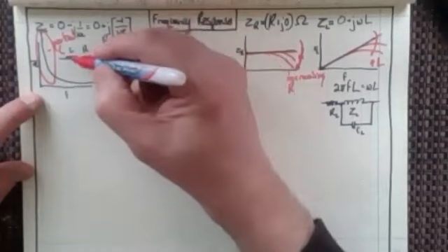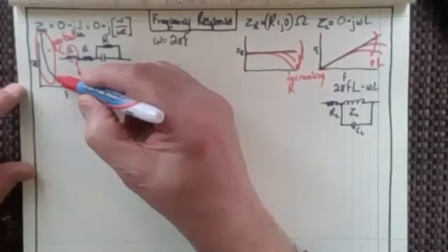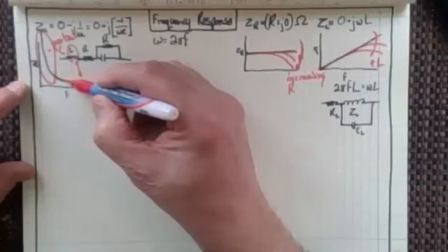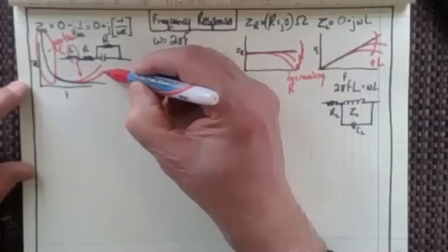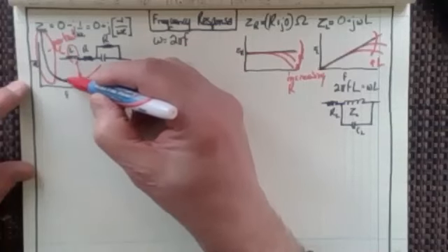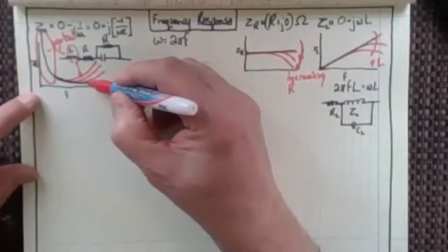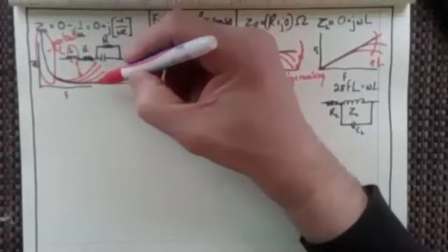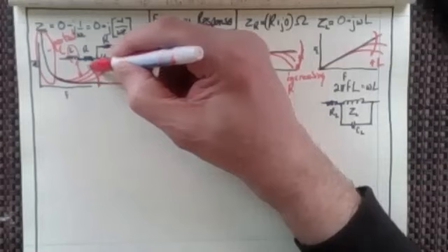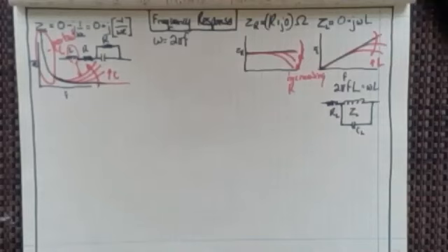Up here, we start to find that the inductive aspect of it starts to come into play. And so instead of having something like this at the very higher frequencies, we start to see the inductive loading come back, and we start to see the capacitor responding more like this than it is like this, right? Which is not the way that it's supposed to. So with increasing capacitance, we're going to see that change in that way.